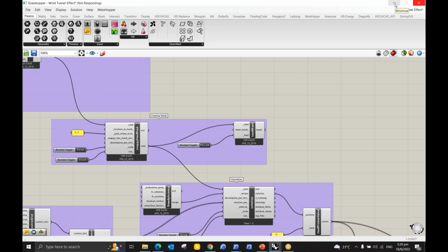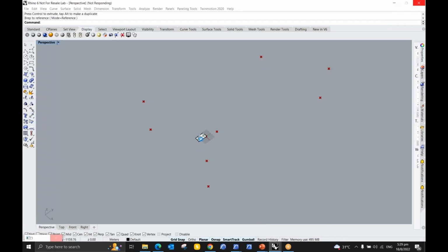It may take a little longer, but what I want to explain here is, if you're doing this kind of simulation where it is performing huge calculations in the background using the CFD libraries, try to have minimum polygons on your morphs. As minimal as possible, so that the mesh created from your morph will not be heavier for performing the simulation in the background.